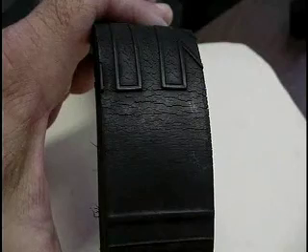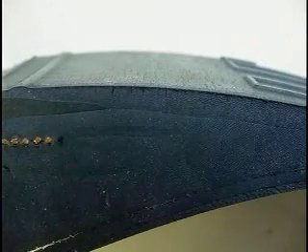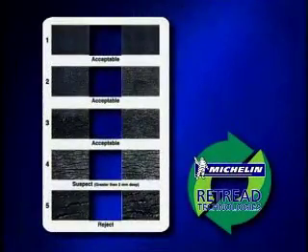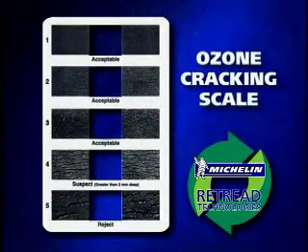Here is a cross-section of a tire with a greater degree of weather checking. You will note that the depth of the cracking is superficial and should not affect the tire's retreadability. There are several sources in the industry for templates and scales which can be used to determine the degree and severity of tire weather checking.